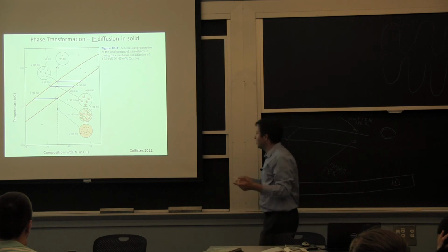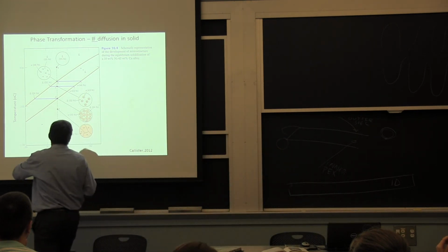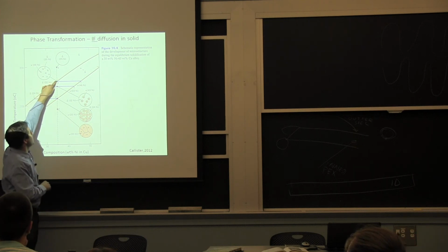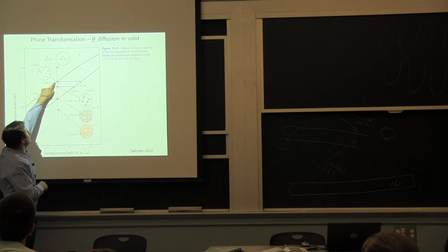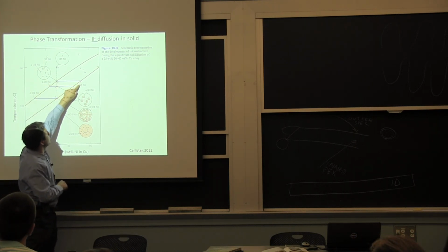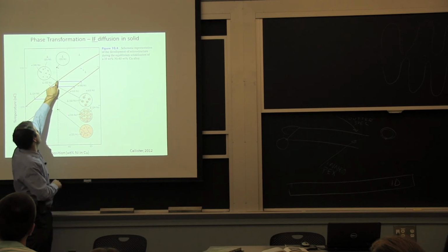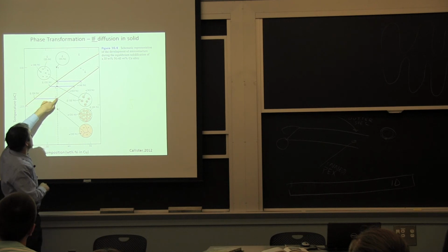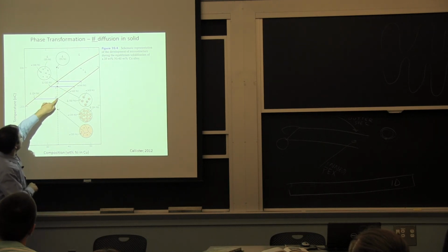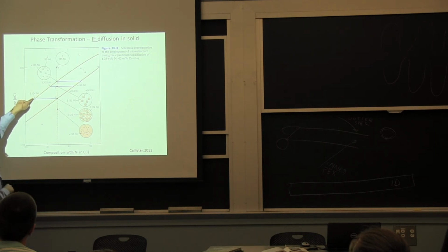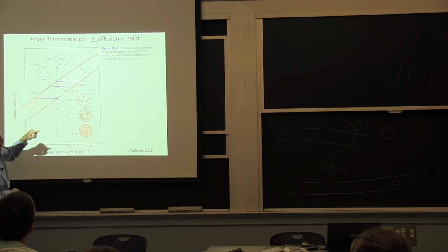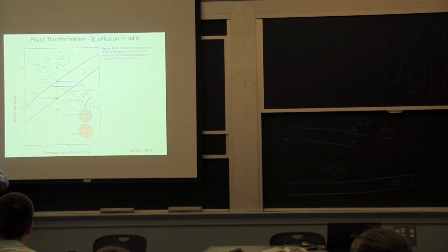And at that intermediate temperature, here we have 35% of nickel, we start to solidify here. So it's going to be a lot more nickel, 46% nickel, and the rest will stay as a liquid. And these numbers keep changing all the way to the last time that you solidify, you're only going to have 24% nickel.